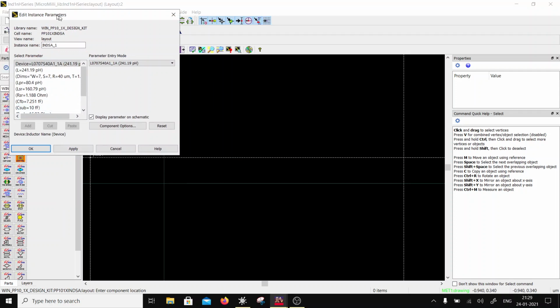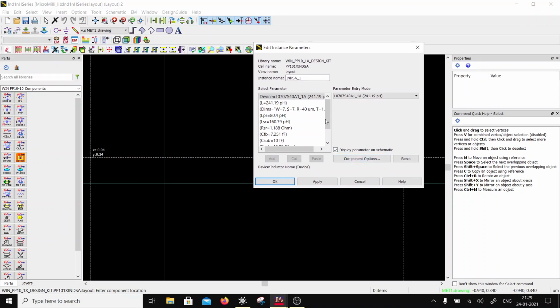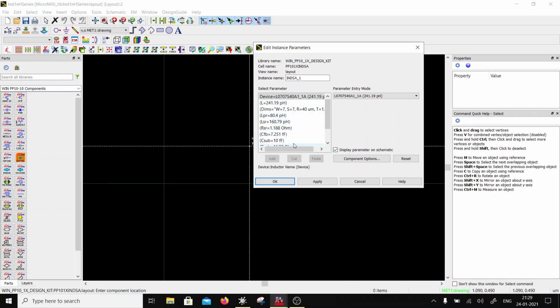I'll tell you what this is. This PDK designer is not doing any math in here. I think he has discrete inductors, meaning they have separate S parameter files, which they got either from measurement or from simulation. So am I going to believe him? No, I'm not going to believe him. I'm going to derive it. So let's look at the inductor.